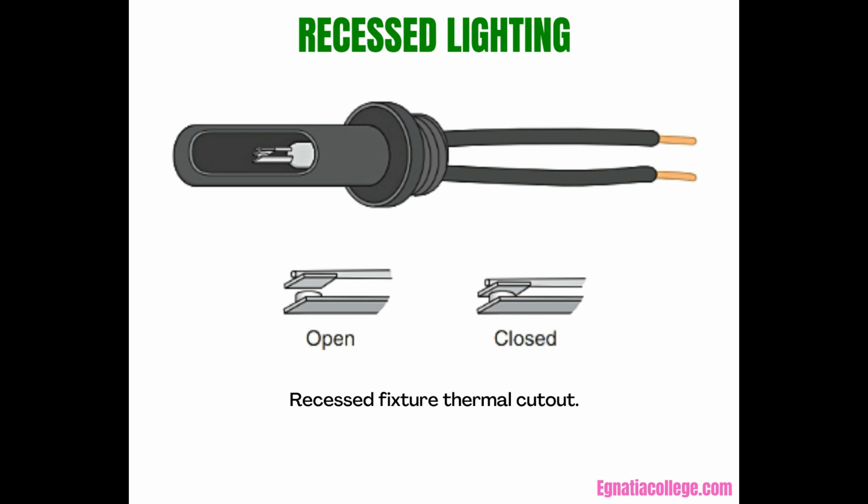Because of the potential fire hazard when mounting lighting fixtures near combustible materials, Rule 30-200-1 states that fixtures must be equipped with shades or guards to limit the temperature to which such materials may be exposed to a maximum of 90 degrees Celsius. If lights are installed over combustible material, each fixture must be controlled by an individual wall switch if it is located less than 2.5 meters above the floor, or if the fixture is not guarded so that the lamps cannot be readily removed or damaged.